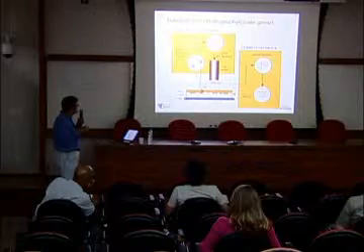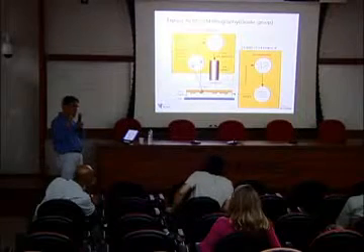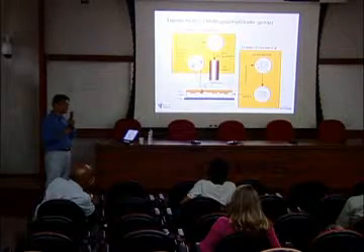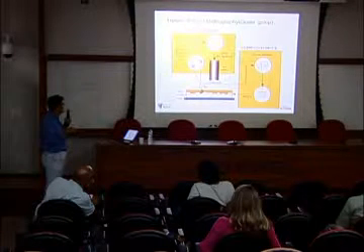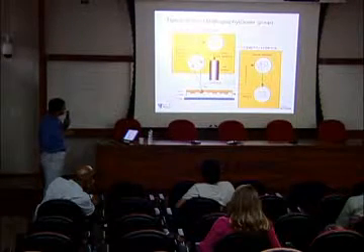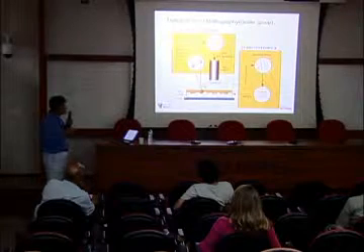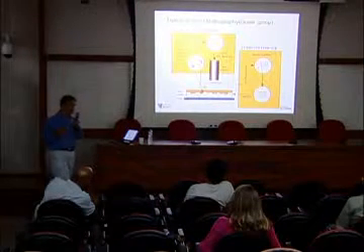XYZ control can be done by the piezo, and also by motors, and detection is done by the laser. The height difference can be measured down to the sub-nanometer level using this laser, and the height can also be controlled in the nanometer range.